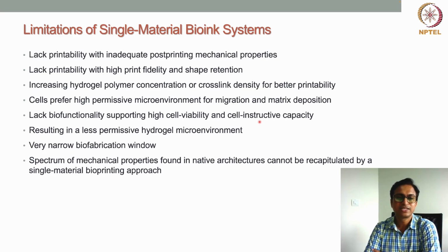In certain cases it lacks printability with inadequate post-printing mechanical properties. We can print with a single material system, but as it is made up of a single material, the viscosity regime of that material can be changed by changing the concentration of the polymer, or the molecular weight, as we discussed in the last lecture. So there is lack of printability with inadequate post-printing mechanical properties. The mechanical properties of the printed structure many a time are not great. So with that, there is a challenge.